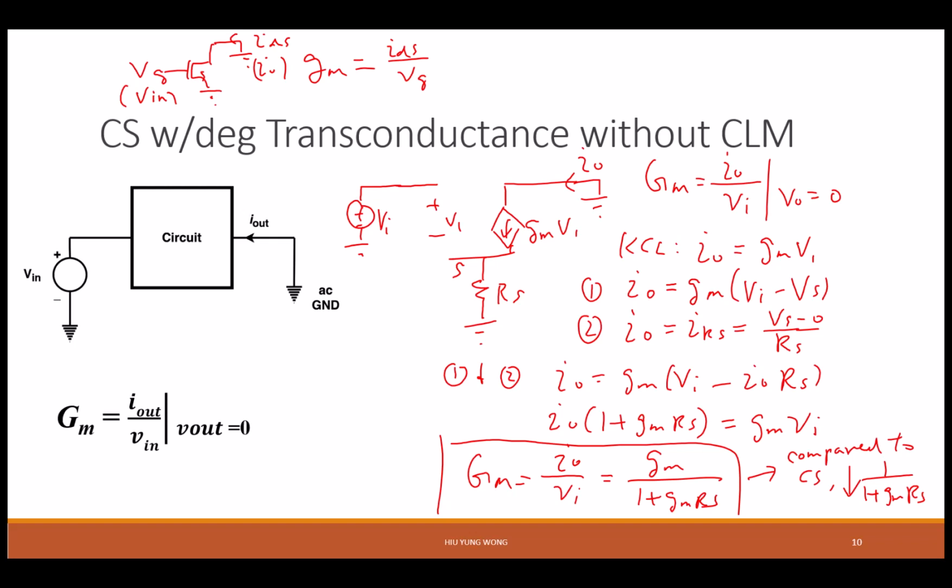Yeah, because it has different terminals. We're not talking about the same terminal. So what current over what voltage? Which current? I mean, what do you care about in a transistor? The gate current or what? The drain current, right? You cannot get it wrong. Drain current over what? Gate voltage.